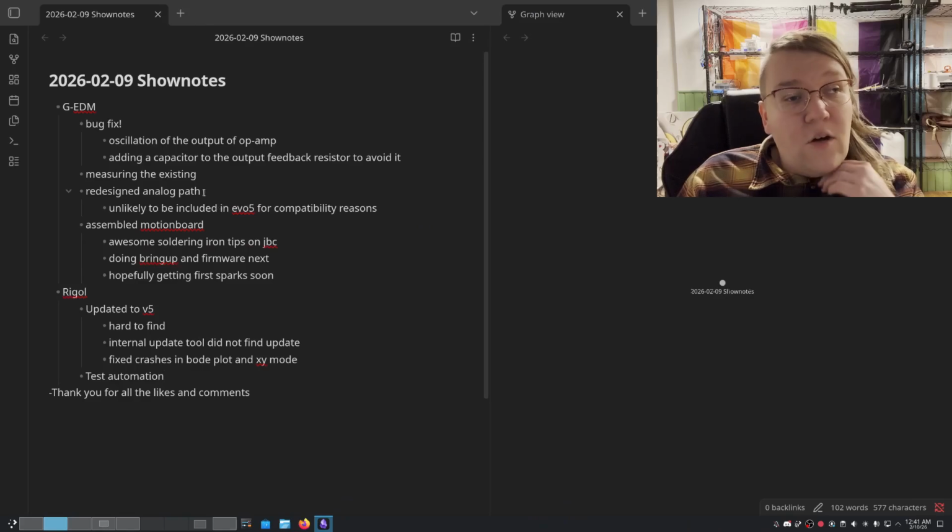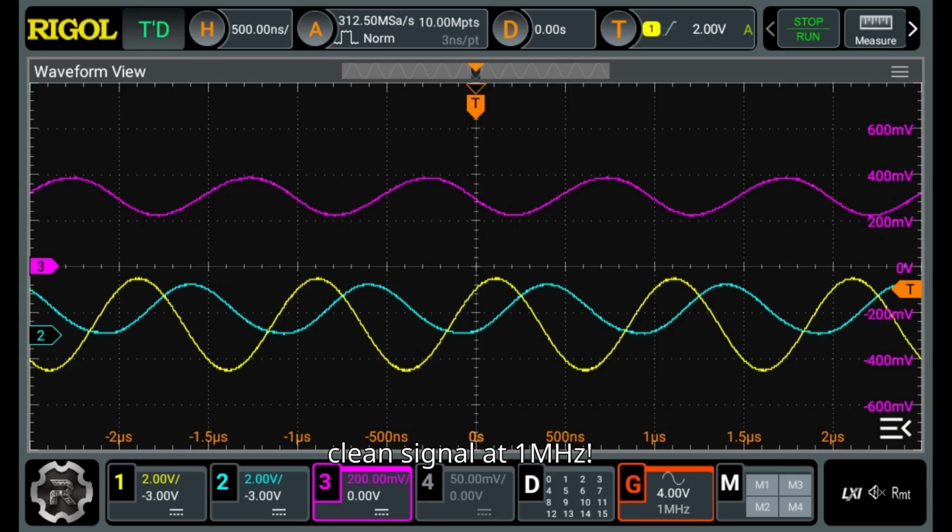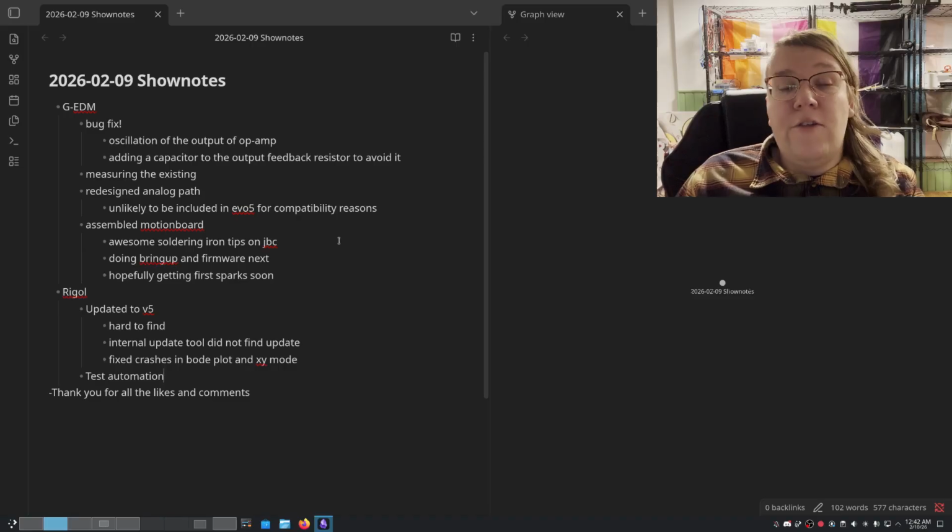In the process of trying to fix this error, at first we thought there was something more significantly wrong, as the circuit is very different from the recommended circuit of the datasheet. We redesigned the signal path and got it working much better. We managed to build a circuit slightly modified from the datasheet that can achieve near 1 megahertz bandwidth with very high linearity, and we got this working pretty well. So we'll definitely document how that works.